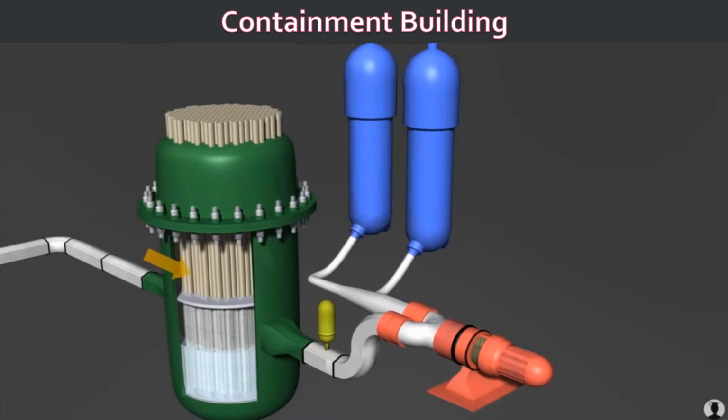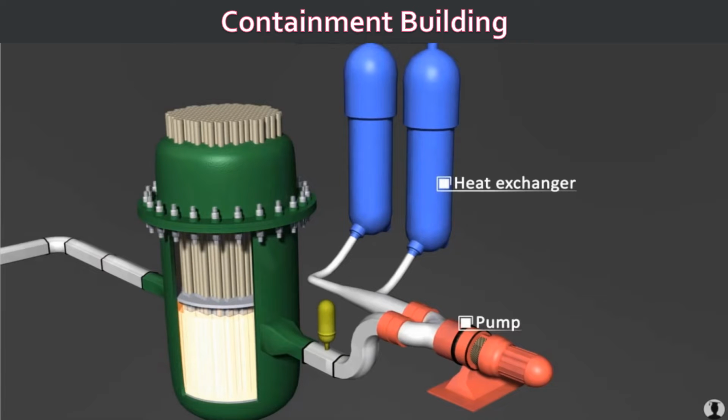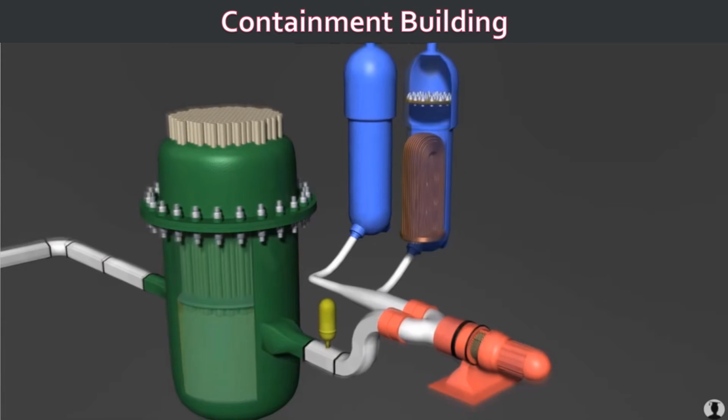And then when it begins to operate, high pressurized water will be pumped into the reactor, and this water is at a very high temperature. It's almost 270 degrees Celsius. So how can it not boil? That is the purpose of the pressurizer. This pressurizer will pressurize the water so that it will not boil even at 270 degrees Celsius.